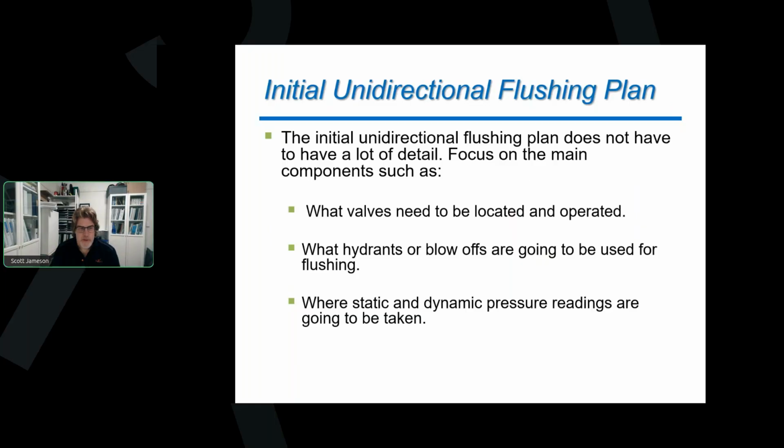So when we're looking at doing the initial plan, right, we've got our map, we've got our list of questions. We're going to really just focus on the very basics right away, right? So what valves am I going to operate to do this flush? Where am I going to flush the water from? So where are the hydrants or blow-offs that I'm going to flush from? And then looking at areas that may or may not have some pressure problems while I'm doing this flush. So we're just going to start with that information.